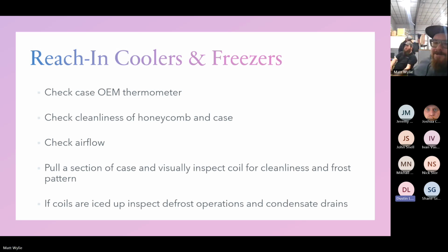But a lot of times, the typical setup is the termination is the first point of ending the defrost, and the time clock is just a fail-safe. A lot of freezers terminate based off of temperature, not off of time, and the time is a backup option. So if your termination Klixon is encased in ice, you figure ice is 32 degrees. If your defrost termination sensor is sitting there encased in ice, it's probably sensing 32 degrees, not the actual coil temperature. You might terminate defrost too soon.